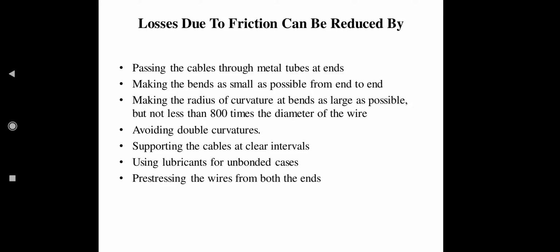Avoiding double curvatures. This depends upon the importance of the member. In some members it is required to provide a cable profile with different eccentricity depending upon the loading condition. In such cases we may have to provide single curvature, double curvature or triple curvature. We should try to avoid double as well as triple curvature, because with the increase in the number of curvatures, there is an increase in the loss due to friction.